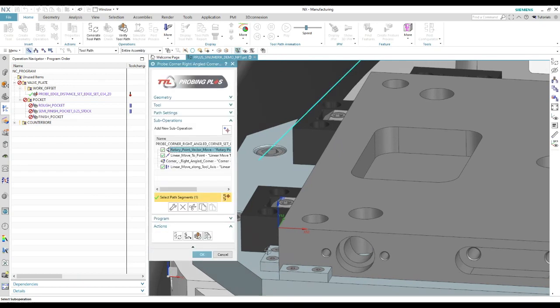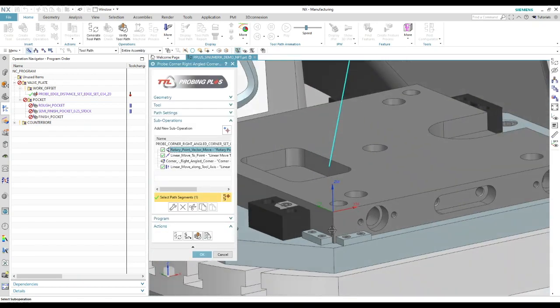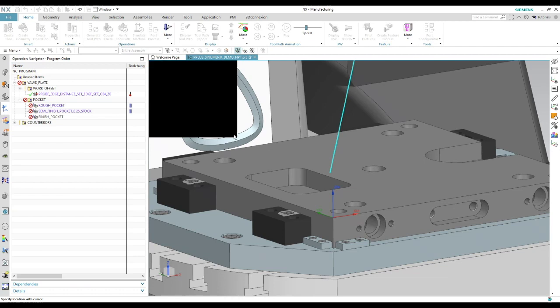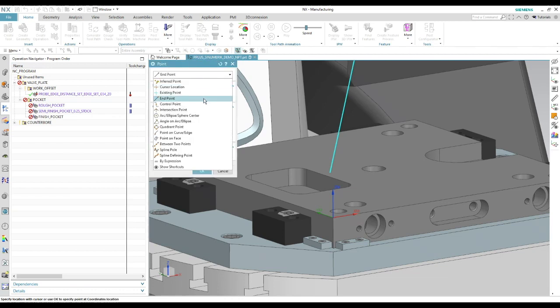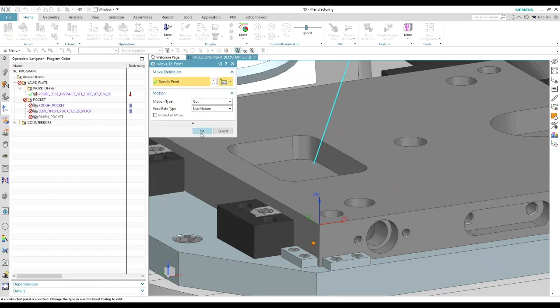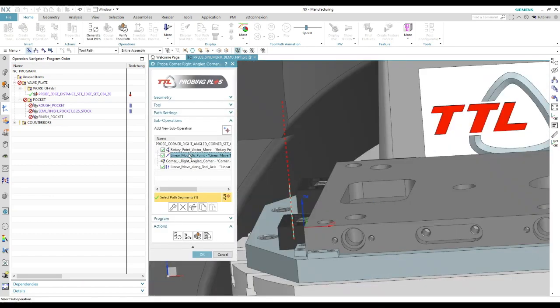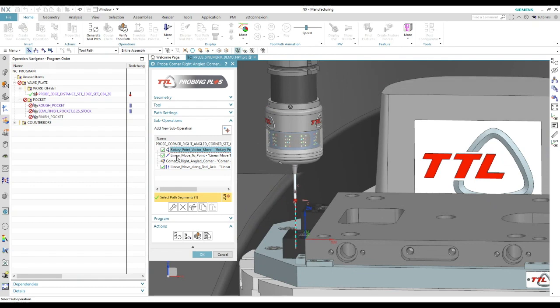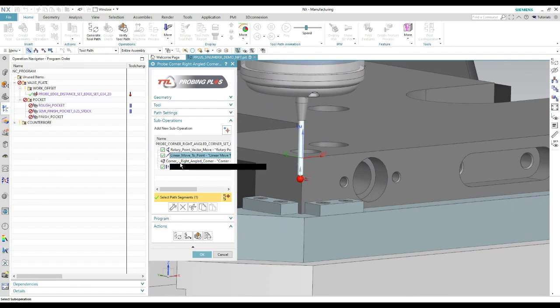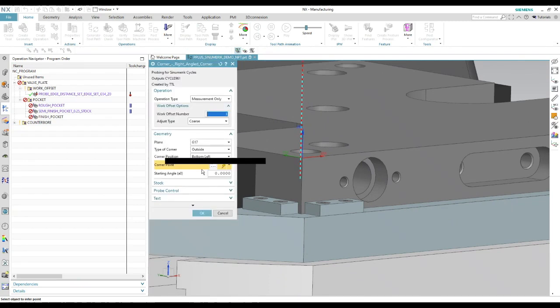I now need to move down in front of this corner position at a suitable Z height to measure the corner. So I'll go into the linear move to point, once again into the point constructor, select the endpoint, this time with a rectangular offset of -10 in X, -10 in Y, this time -10 down in Z. So this is where we're going to wrap it to and move down to a suitable position to probe this corner.